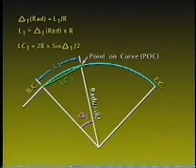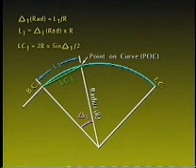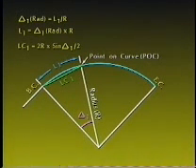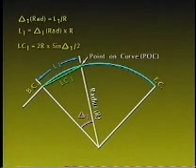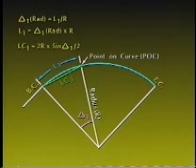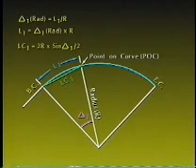This graphic is used to show how a particular arc of curve can be divided into a sub-arc length, L sub 1. Sub-arc 1 starts at the BC and runs along the curve to POC sub 1. Therefore, subarc 1 will have among its other elements delta sub 1, long chord sub 1, and deflection angle sub 1. These values are always unique to their particular arc. Before proceeding into curve layout computations and layout procedure, let's take a look at some other elements of a circular curve, keeping in mind that all elements of a curve are mathematically related.